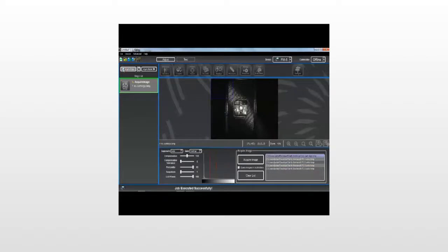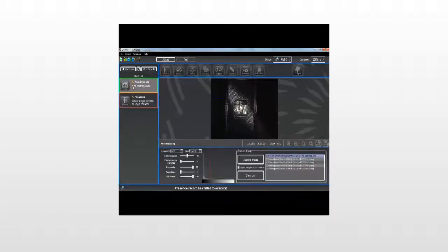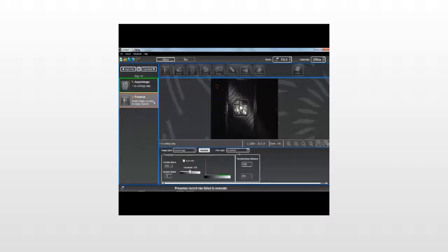This first image is just the background in the test fixture that we use. I think I'm going to start there, and the first thing I'll show is our presence-absence step to see if the cartridge is even present in the image. So we're going to add our presence-absence step. Now the first thing you see is you get an invalid image, since I was using color images here, but this step requires a black and white image.